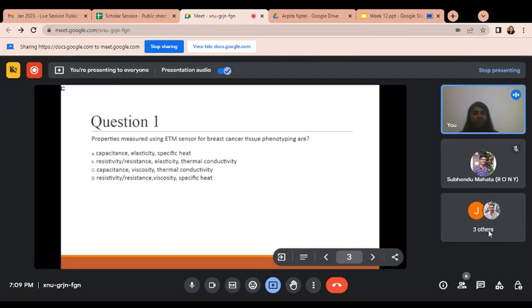If you want to remove organic or inorganic contamination from the wafer, we use different types of wafer cleaning processes. First, piranha is a wafer cleaning process to remove organic contamination from the wafer. We prepare the solution of H2SO4 and H2O2 in a 3:1 ratio, dip the wafer in it, and after some time we take the wafer out and dip it into DI water.